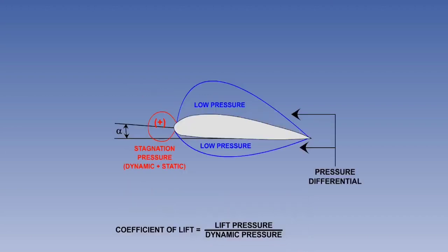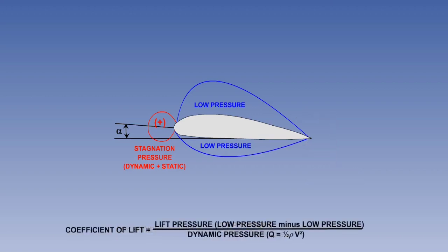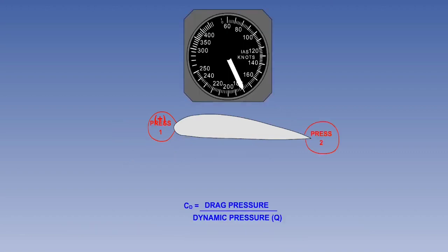A coefficient is a number without unit or dimension expressing a degree of magnitude. An aerodynamic force coefficient is a common denominator for all aircraft, regardless of weight, size or speed, and is a ratio between the average aerodynamic pressure and the airstream dynamic pressure. By this definition, a lift coefficient, or CL, is the ratio between lift divided by wing planform area, or lift pressure, and dynamic pressure. A drag coefficient, CD, is the ratio between drag divided by wing area and dynamic pressure.